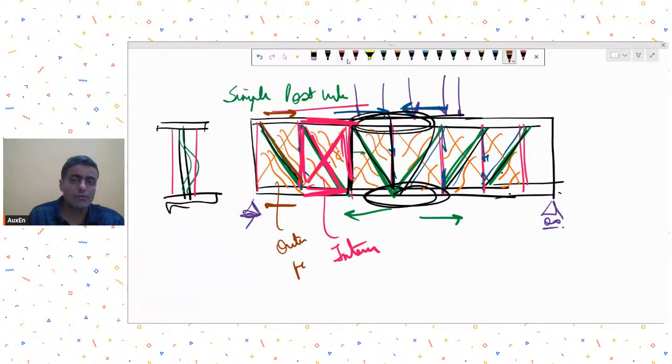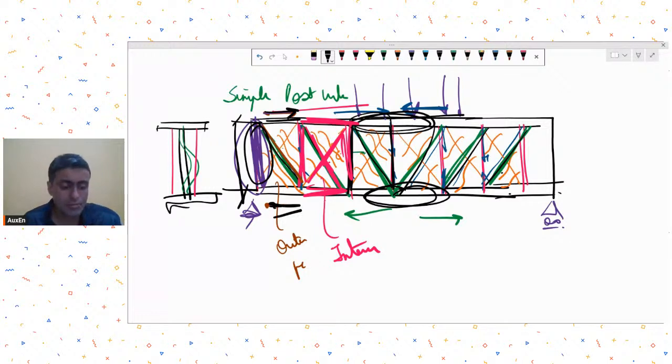So now what you have to do is that these stiffeners that you provide at the end, this end stiffener has to be designed to take the force that you have in the chords. This stiffener has to act as a beam, imagining that this was the span of that beam, and the forces that are being generated in the top and bottom flanges. So this stiffener has to be designed for it. This is called designing the stiffener for anchor forces.